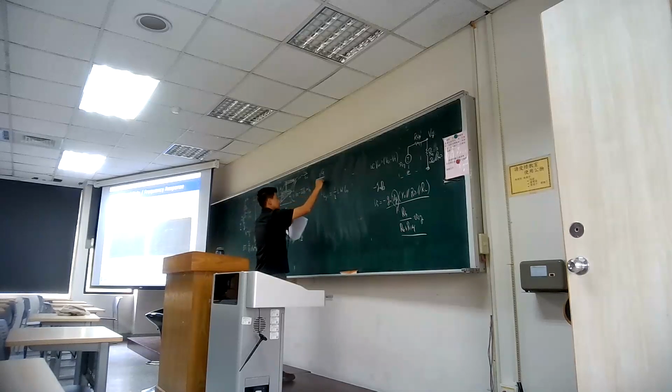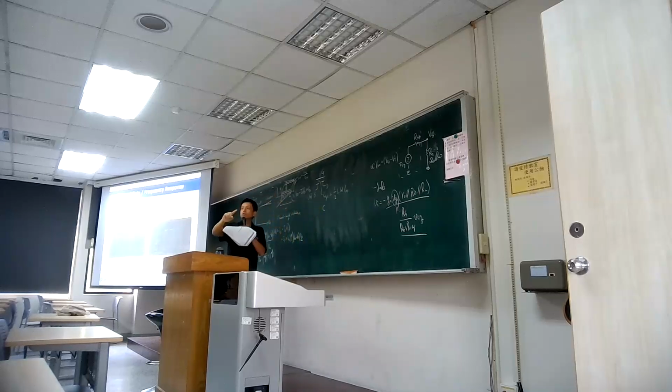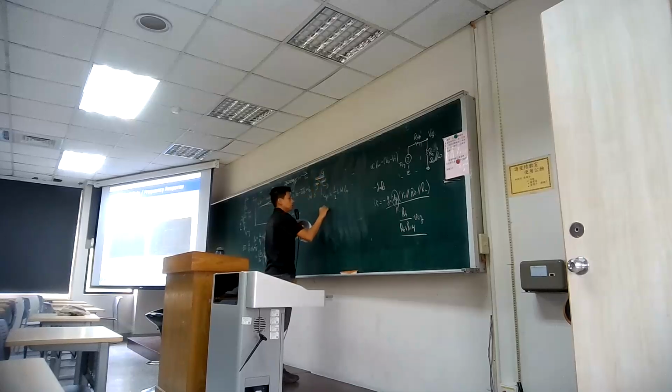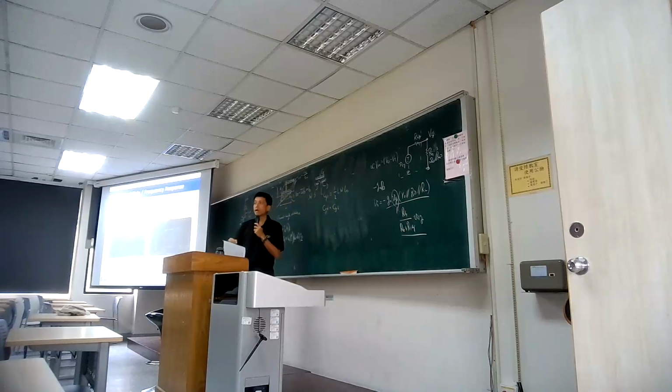Okay, and then if you consider there's another capacitance which is the drain capacitance, we can say if it is in inversion, so we just first consider it's inversion without applying additional drain voltage. So your charge will be uniform along the channel. Okay, so let's just consider we get a negative charge here, we get a positive charge here, without applying VDS along the channel. So CGD will equal CGS equals 1 over 2 L W C oxide. Okay. And then in the situations,